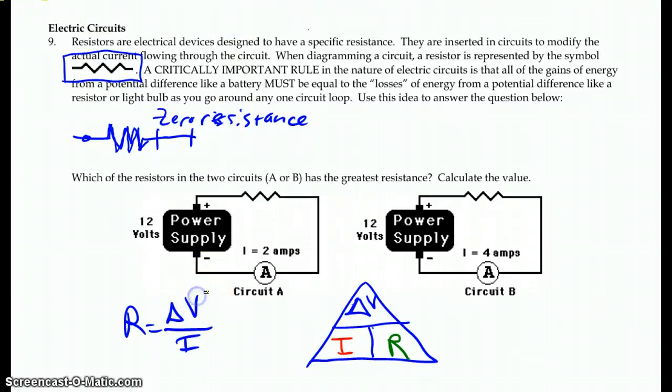Okay, in our case, we're putting in 12 volts, so it's 12 volts of potential difference. That's the measure of the energy we're putting in. It means we're putting in 12 joules of energy for every coulomb of charge that moves around. And then 2 amperes is the amount of current. So 12 divided by 2 is going to give us 6. And when we divide volts by a current, we get 6 ohms, symbolized by the Greek letter capital omega. On the right-hand side,